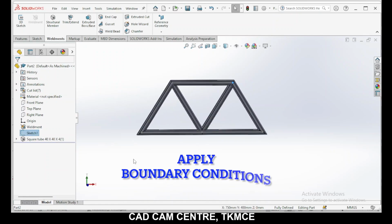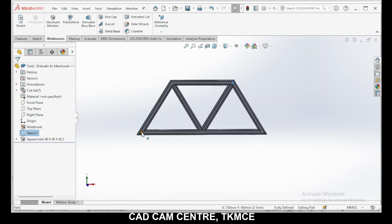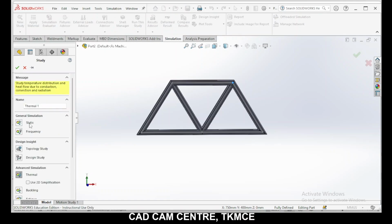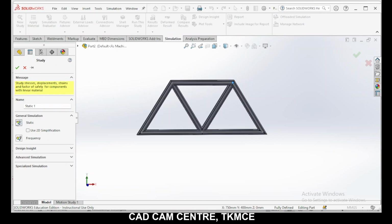Now we have to apply the boundary conditions like the joint features, degrees of freedom at the joints, and the forces acting on joints. Let us first fix this. For that, you come to simulation, go for study. We choose static problem.